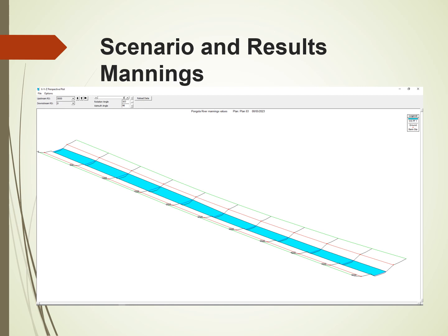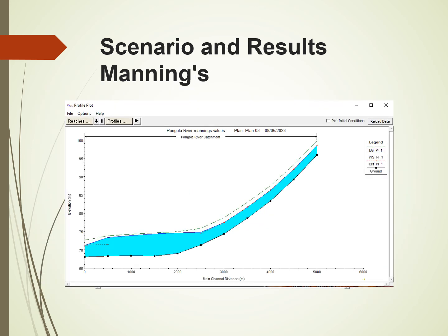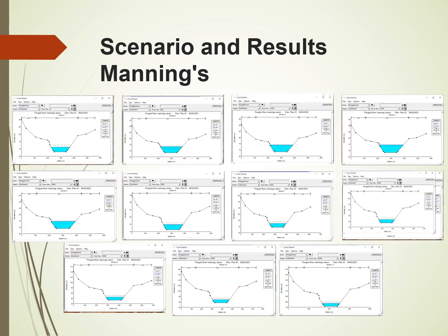So over here on our 3D output, we can see the water level has subsided quite substantially with a slower flow. On our profile plot, we can also see that the water level has now dropped a bit, especially on the downstream side, even though it is still backed up quite a bit because we're entering that area where the velocity has been slowed down.